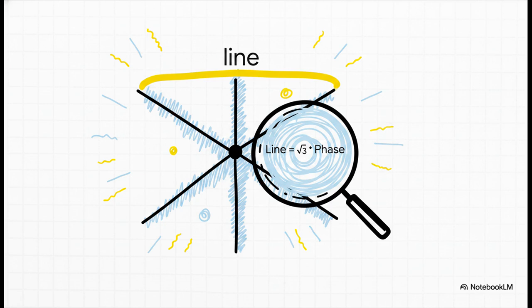Our final exam problem looks at balanced star-connected loads. In three-phase power systems, which is how commercial power is actually generated, a star connection is foundational. We need to deduce an expression relating the overarching line voltages to the individual phase voltages. Because the three power phases are perfectly offset by 120 degrees, the line voltage mathematically proves to be exactly the square root of 3 times the phase voltage. It's a brilliant piece of engineering logic.